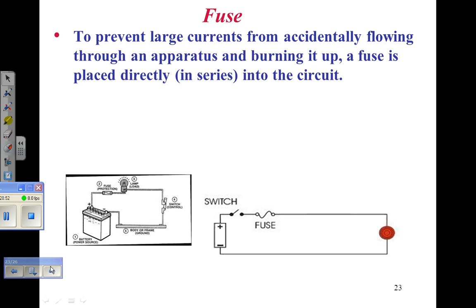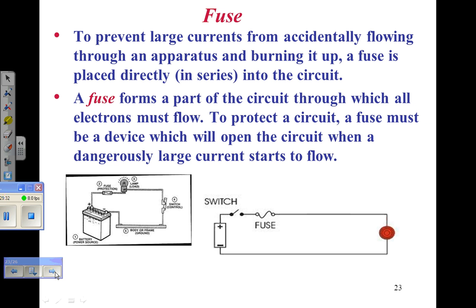Especially, now we have instant trip. We have 4 things. We have instant trip circuit breakers and instant trip fuses. A little bit too much over whatever its set point is, when it gets that amount over, it trips, period. With an inverse time breaker or a dual element time delay fuse, there's a time delay between the overage and when it kicks off. There's that inverse time thing that happens, and fuses are generally used to start motors, so it lets a big overflow happen for a short period of time. But if that continues on, it will blow. That's why fuses are used to start motors almost all the time.